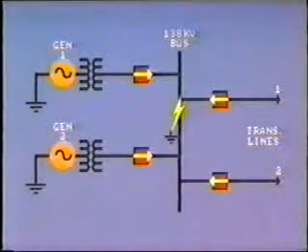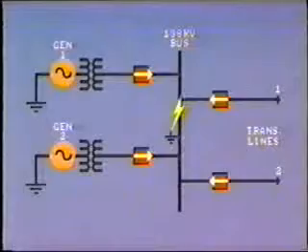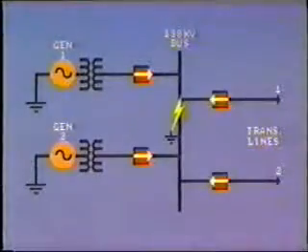The current flow in the transmission lines would reverse and feed into the faulted bus. With such high fault capacity available, the resultant damage could cause a prolonged outage for repair, with the consequent loss of availability of generation and the 2 transmission lines.